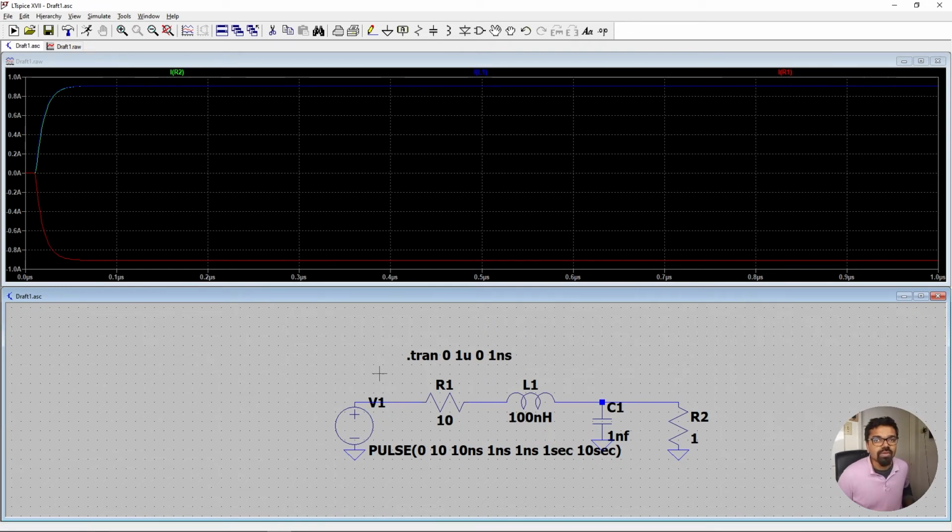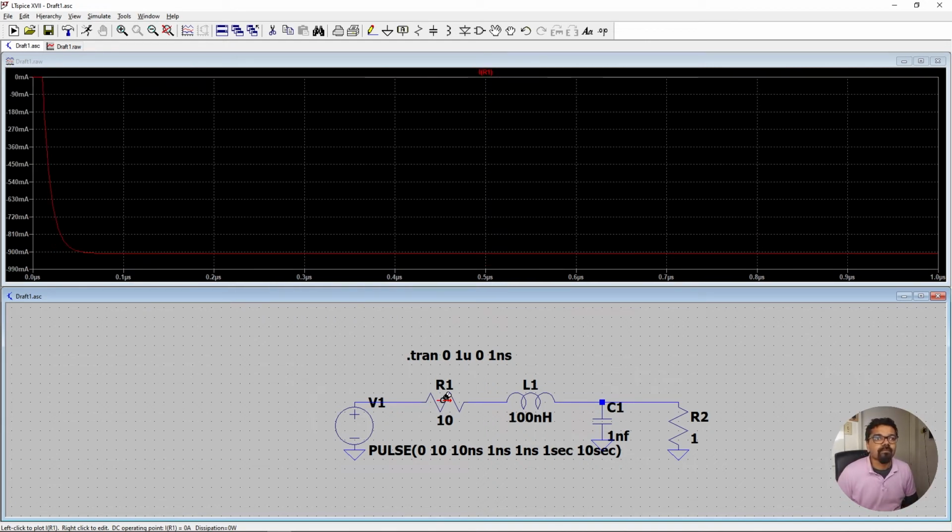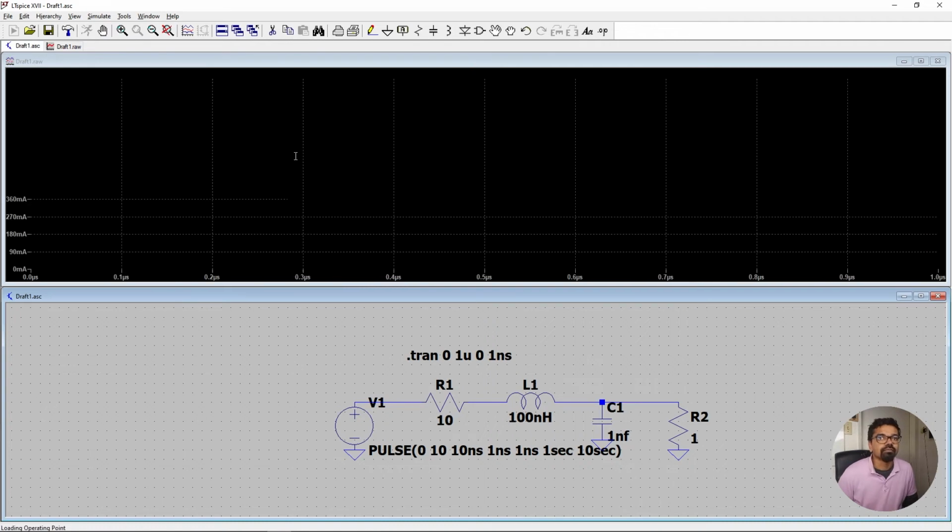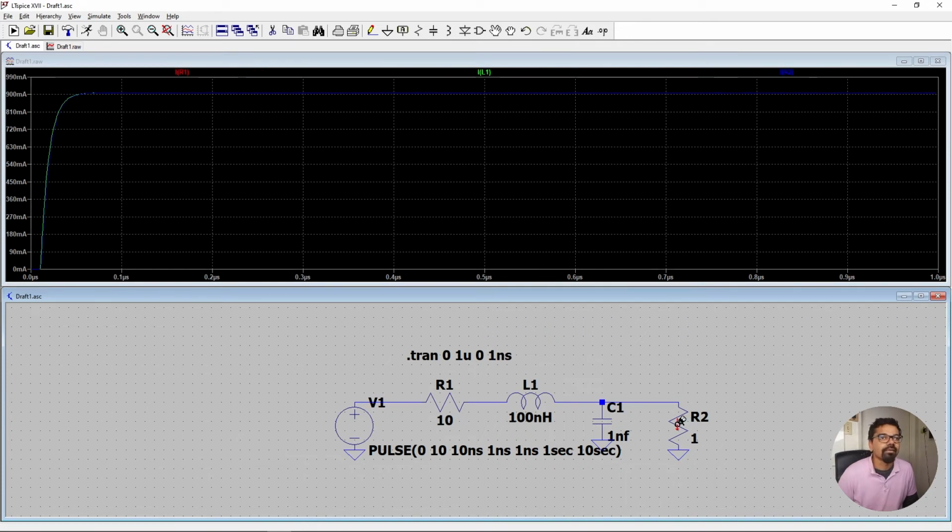And I think it has to do with the fact that maybe if I cut this and then do a control R, it's maybe the way I place a resistor. And now if I do this, yeah, maybe I should simulate this again, run the simulation. And now it's looking a lot better. Now they're all the same. Yeah. So it's basically the orientation of the resistor that makes a difference. So the current flowing through all of them is the same, which is exactly what we want to see.